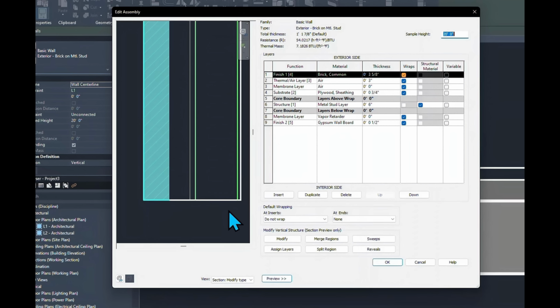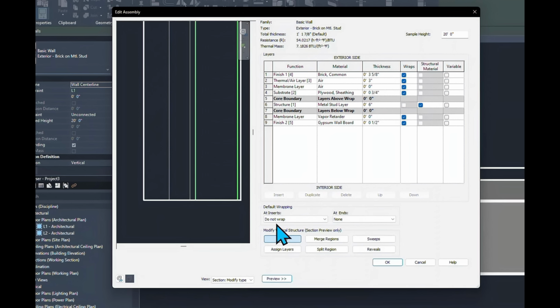And this one is going to give you the ability to select the bottom. But in order to do that, you need to basically go to modify. So you can see right here in the modify. When I click on the modify, if I hover over each of these layers, you guys can see these are kind of divided with a different section. So that means that I can unlock this layer because if I select on this, there's going to be a lock over there. And each layer that this wall is created because of the different material has a different layer.